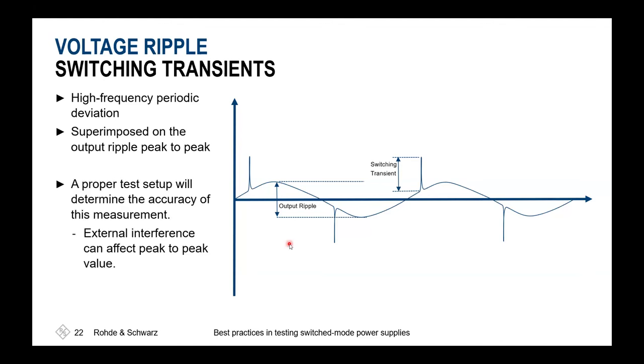So it's very important to always think about what am I expecting inside my switch mode power supply as the steepest edges. And with this, you will get a definition of your needed bandwidth of your oscilloscope and probing solutions at the end.